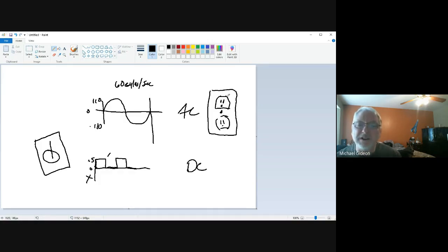If you've looked carefully, you'll notice that one of these is longer than the other one. Typically, not always, newer ones are. That's showing us which one's the hot one. The little one, that's the dangerous one. That's the one that's going to bite us. The big one is the return line. We need both to make it work.